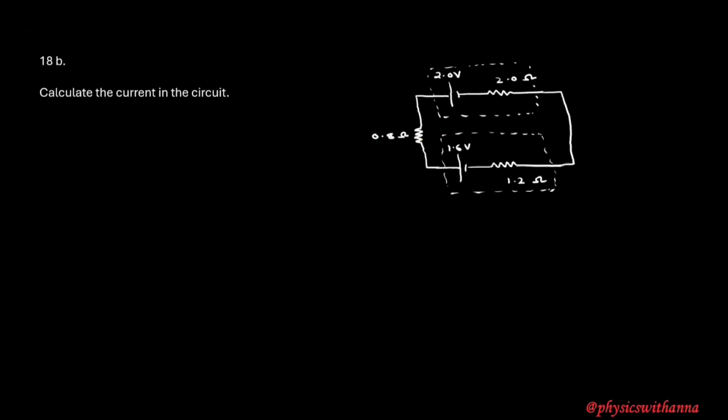Then we do the same thing in the next problem. I'm going to use Kirchhoff loop rule again to calculate the current in the circuit. So let us start with showing direction of current. I will take the current coming out of the bigger battery from its positive terminal. So now this is the direction of current, counterclockwise. We call it I. Then we choose direction of traversing. I'm going to take it in the same direction as the current, again counterclockwise.